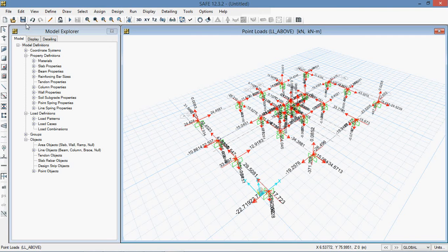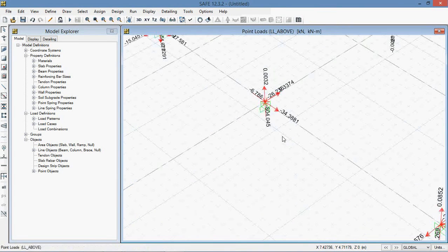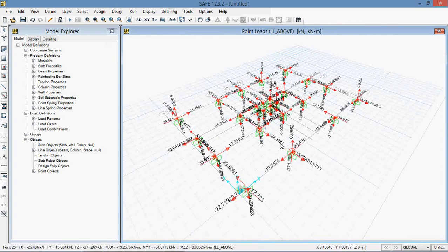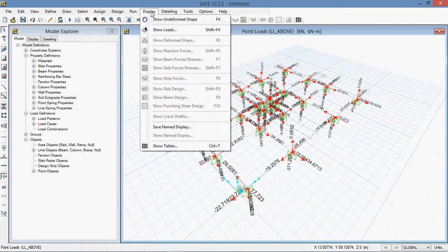Okay, if you have to design the isolated footing, one way is you can select the highest of all these values and provide that value in the mat. For example, you can just design one isolated footing and provide it everywhere. This is one choice. The other choice is that you provide the footing under every column, and then we see either the isolated footing is working or not, or we have to go to the combined footing.